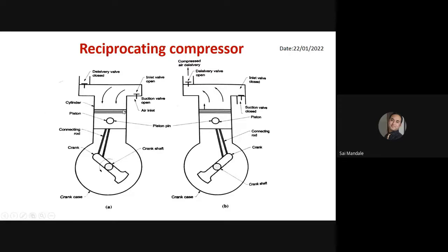And once it comes down, there is one fixed position of the cylinder so that it can come down to that maximum particular point. That point is called BDC, that is bottom dead center. One is top dead center, the maximum reach of the piston, and one is bottom dead center, the minimum. So as this piston is continuously reciprocating inside this cylinder, it is reciprocating between TDC and BDC, top dead center to bottom dead center.